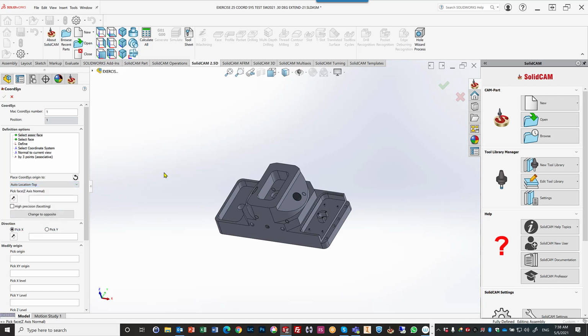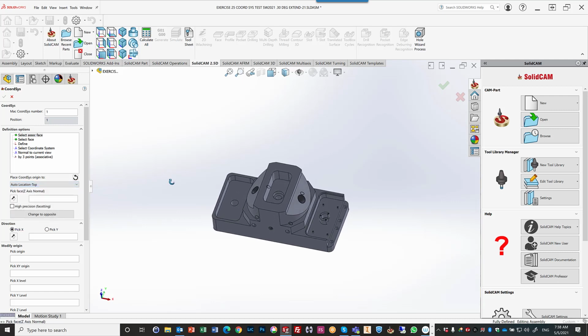What does that mean? If I go now to this field and click over here, auto location means it'll go to the closest point on top to that corner. You'll note when I click, we get the automatic box, and we have hot points on that automatic box.